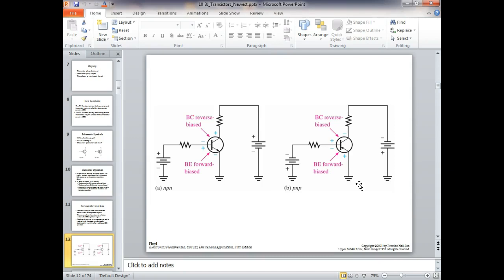You have to understand there is a path for the current to get through. So it's not like a switch, because when you open a switch, there is no path. You're breaking the circuit. Here we have a path. Now it's extremely high resistance, but there's still current flow through that. And then when we put over 7/10 of a volt on it, it will start turning on, and then it goes into what we call the active region. In the active region, it acts like a rheostat, and what does a rheostat do?